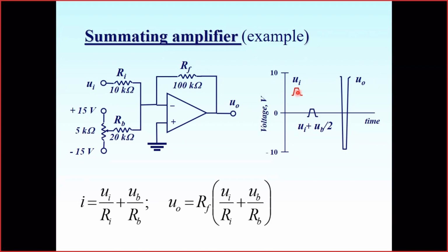So what actually happens? Imagine if I take this shape and presume that it's drawn on an elastic sheet, and I try to pull it out. So it actually goes up. Or, if it is easier for you, just think what happens if I multiply this curve by some number. It goes up, but the DC, this basement, grows too. And because of the basement growth, my whole graph multiplied by something will very fast reach the maximal voltage that the amplifier may produce.